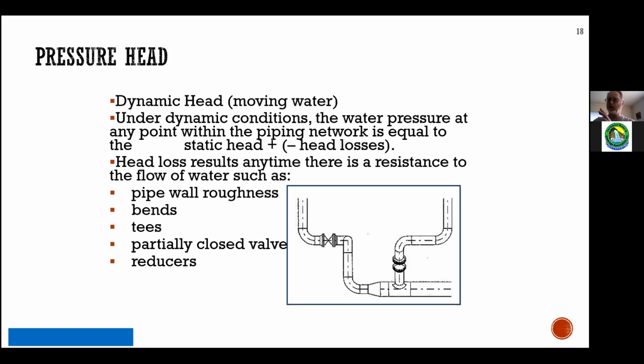But when you put a pressure gauge on it, it'll be the same. Or it'll be the same under static conditions, but as soon as water starts to move, that dynamic condition, the energy is robbed. So from an operations perspective, it's not just about building the reservoir high enough or sizing the pump appropriately. Every connection along the line between the supply and the customer has to be taken into consideration. And as operators, we can impact all of this on a daily basis.